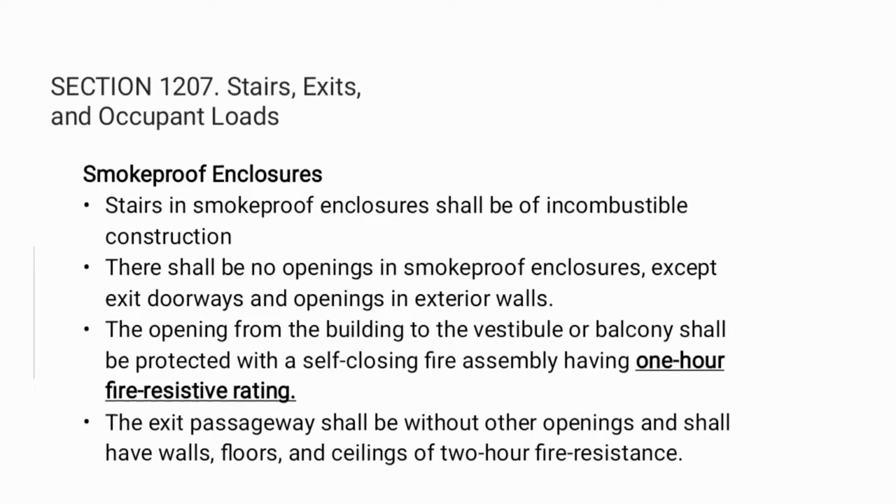Next is the smoke-proof enclosures. So stairs in smoke-proof enclosures shall be of incombustible construction. Second one, there shall be no openings in smoke-proof enclosures except exit doorways and openings in exterior walls. Third one, the opening from the building to the vestibule or balcony shall be protected with a self-closing fire assembly having 1 R fire resistive rating.